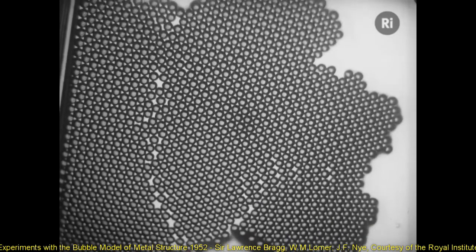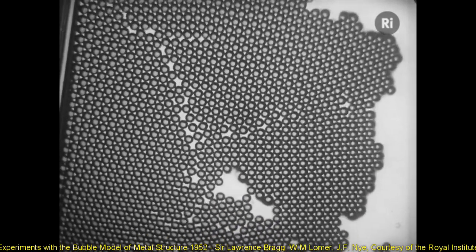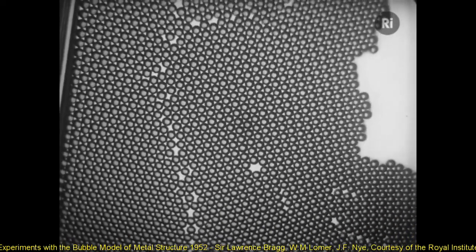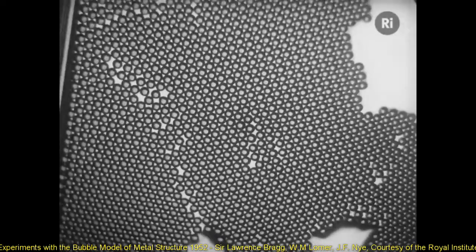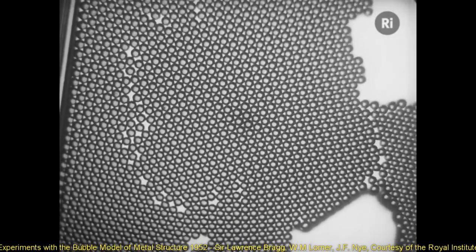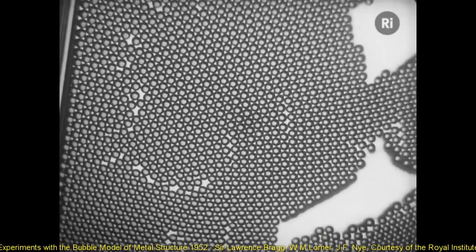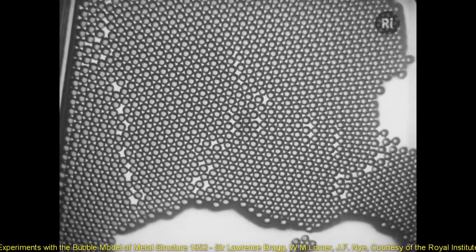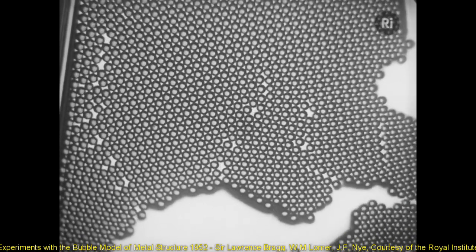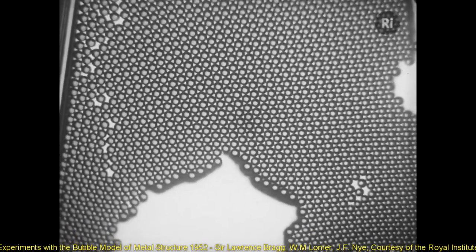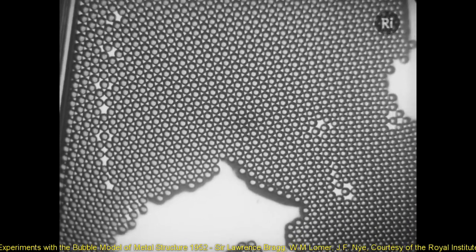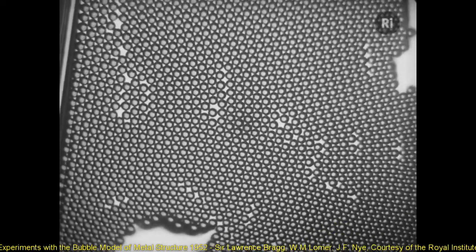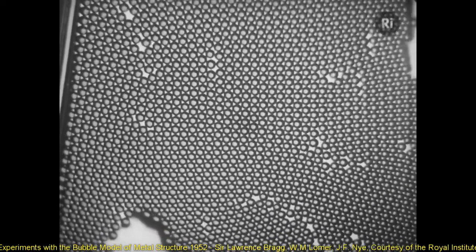Dislocations segregate along the boundary lines in order to result in a lower boundary energy in our polycrystalline material, or bubble raft, as shown in this model. If we apply a stress to the edge of this bubble raft, we'll see that boundaries will react to this stress and may result in this boundary going to the edge of the raft where it may disappear. Grain boundaries may also combine as a result of this stress to form new boundaries.